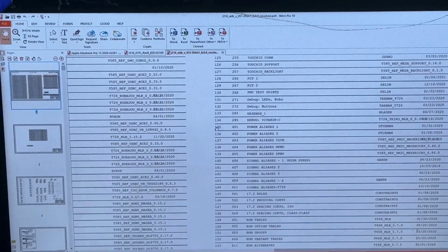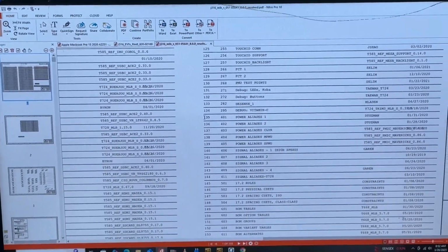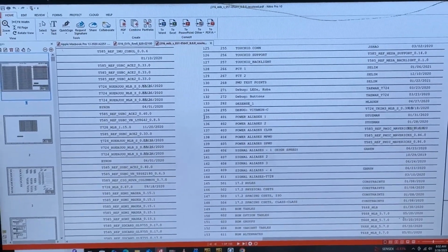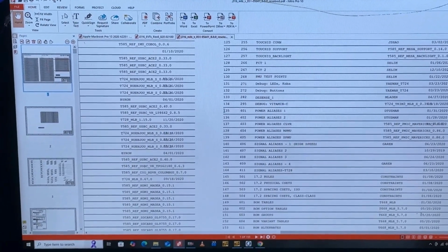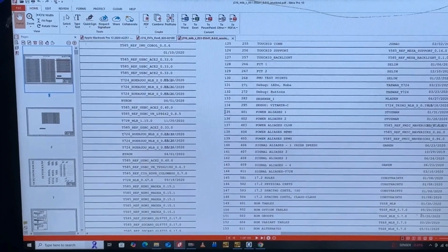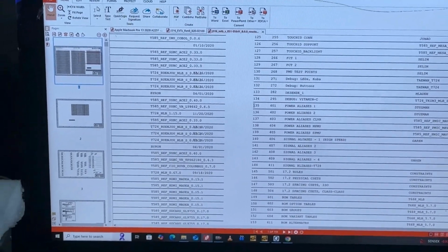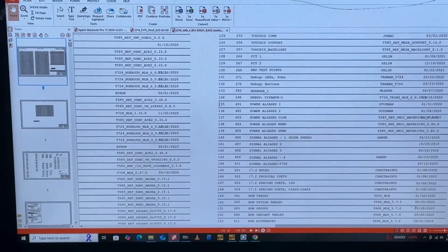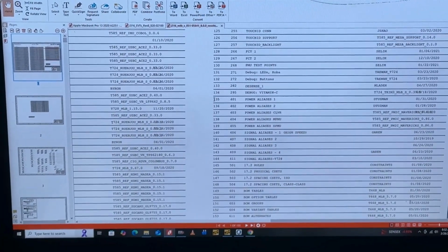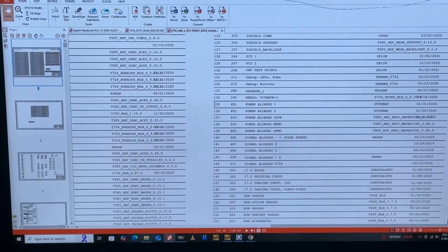The power alliance is a collection of the powers built on this motherboard to make it function. We have the PP3, PP bus, PP5, PP1 and all the rest. There are many voltages that are meant to make a motherboard function.